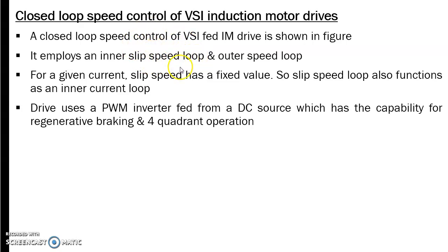Before proceeding, you should understand what slip speed is. Slip speed is nothing but the slip into synchronous speed. All of you know the slip equation: S equal to Ns minus Nr by Ns, which is equal to slip. From that equation, Ns minus Nr is equal to slip into synchronous speed.